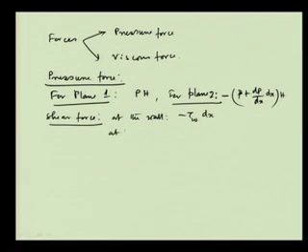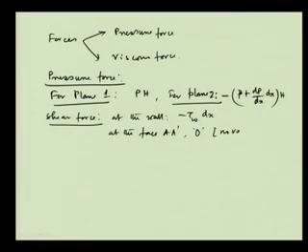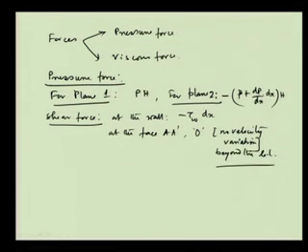At the face A dashed, what will be the shear force? Zero. The reason is that shear force means tau equals mu into dV/dy, and there is no velocity variation, because it is beyond the boundary layer.